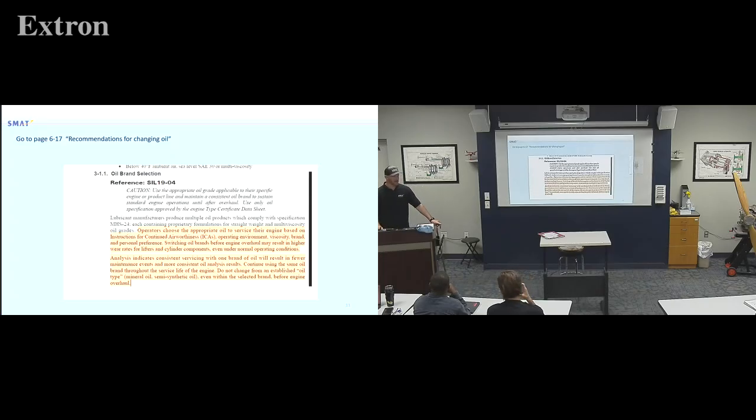Oh yeah, I saw a hand over here. So it says don't change from mineral oil to synthetic oil. Yeah, so they don't want you to go. Does that not count then for break-in? So that's going to be more following the break-in instructions, up above or maybe below. It'll say use this oil for break-in and then switch to whatever one you want. What they don't want you to do is switch back and forth and back and forth. But yeah, great question.